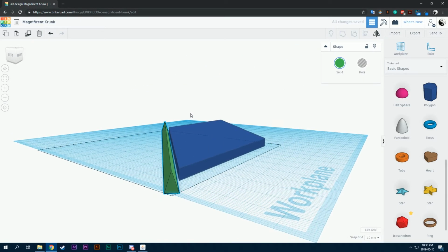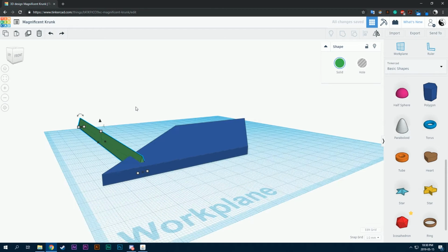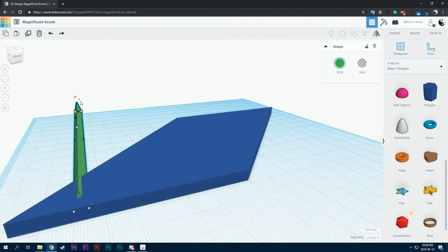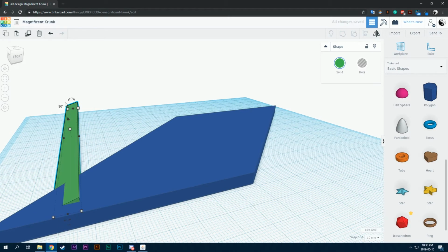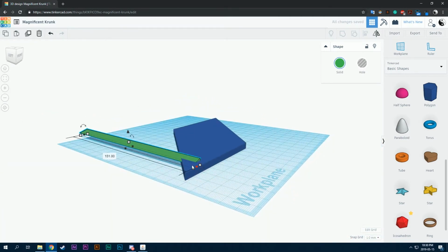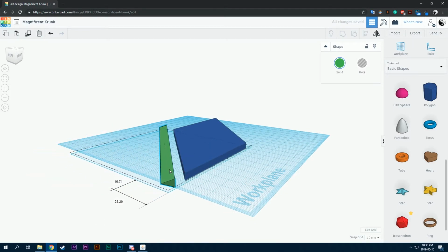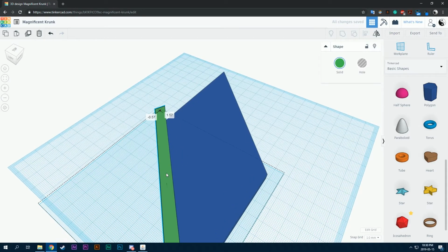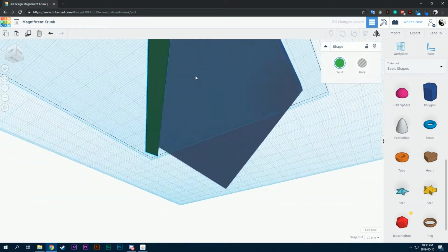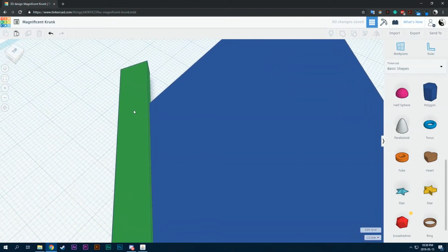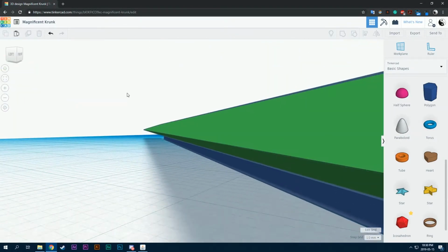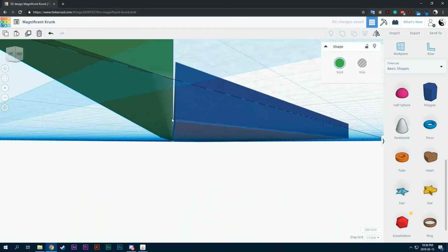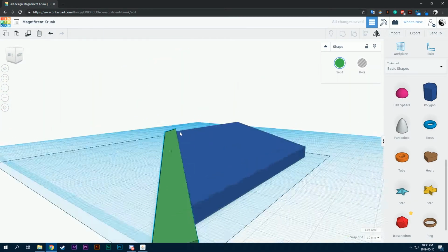And then you can take this rotate, or my bad, I guess you have to rotate this first by 90 degrees. So that's a simple 90 degrees. I just typed it in. And then you want to rotate this by 45 degrees, which allows you to now place the object almost perfectly on the other fin. Now if you look closely, it's a bit tall, so you can just take this and drag it down to about the 0 point.